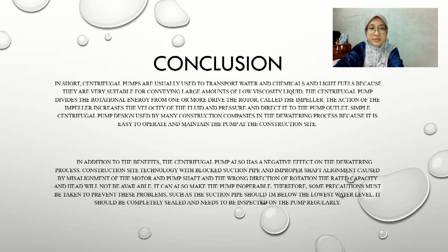Therefore, some precautions must be taken to prevent these problems, such as the suction pipe should be 1 meter below the lowest water level. It should be completely sealed and needs to be inspected regularly.